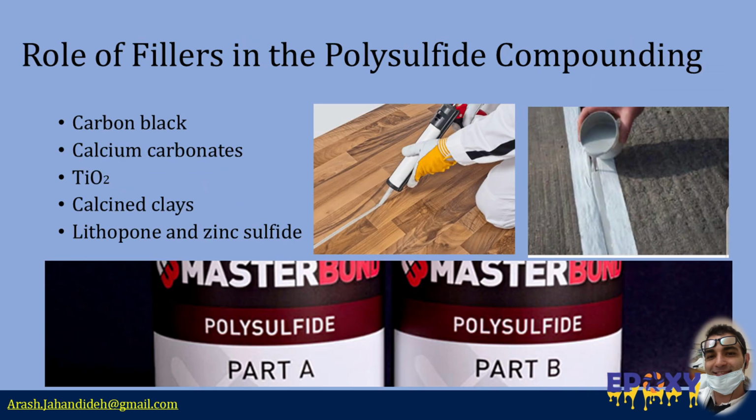Now let's look at the role of fillers in polysulfide compounding. Carbon black is primarily used in aircraft-grade compounds. It contributes to higher physical strength and durability, key performance characteristics in demanding aerospace environments. For most other applications, calcium carbonates are the primary fillers.